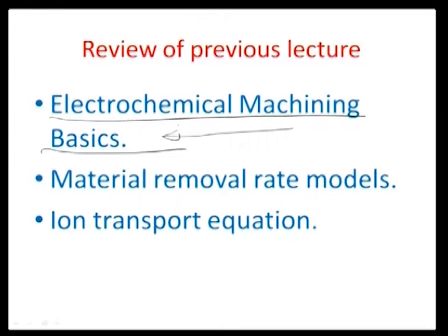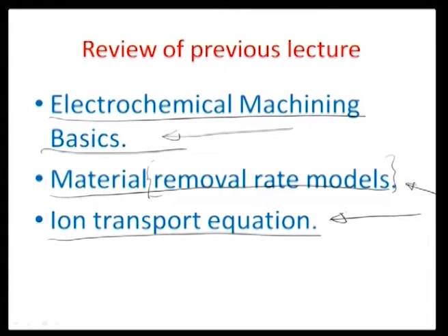So, we also did some estimation of material removal rate, and we studied Faraday's law in the process. We were yet to predict what amount of material per unit time may be removed by this process when we started looking at the very first important thing in electrochemistry or in any electrochemical operation, which is the ion transport equation.